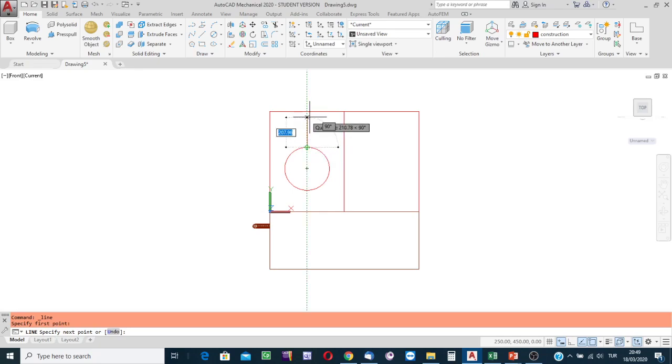Indicated, and create the line. It is going to be an inclined line. Its length, let's say, 120. Clicked on tab key, inclination angle into the box, write it, say that is 50 degrees.